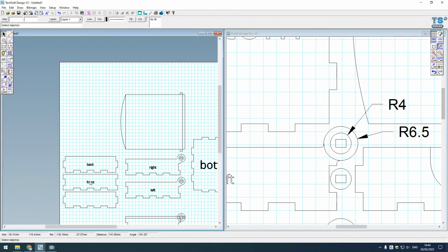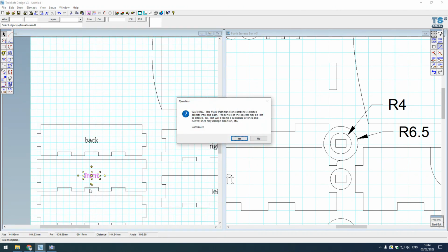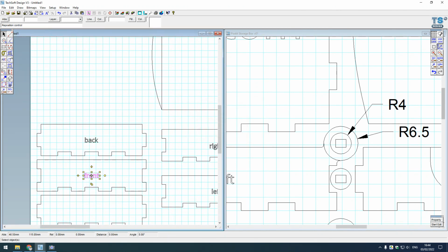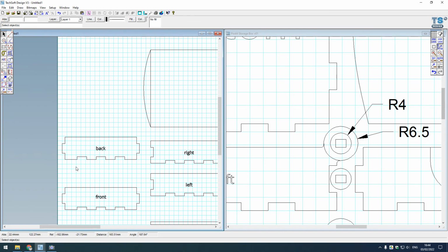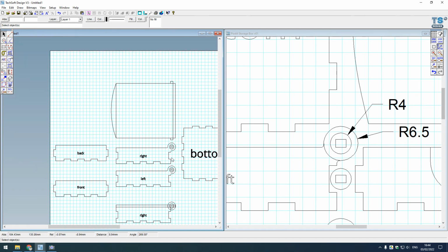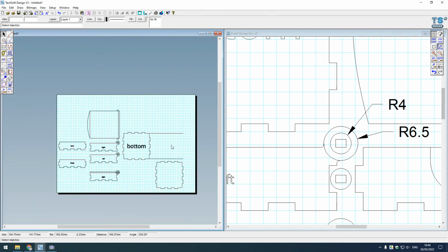Of course, it means that I don't want to get mixed up here, because I don't want to have 3 of these panels with the finger joint cut out in the middle. I want to have 2 of those and 2 with the finger joint sticking out. So effectively now this panel here is wrong. I'm going to select that front, Control H to group it together, or make it into a continuous polygon, bring that down, and I want to get rid of that so that I am left now with my front and back and my left and the right with the hinge mechanism in place. And I've got here the pins of my hinge, which are going to fit into these little sections. Okay, so that's looking really solid now.